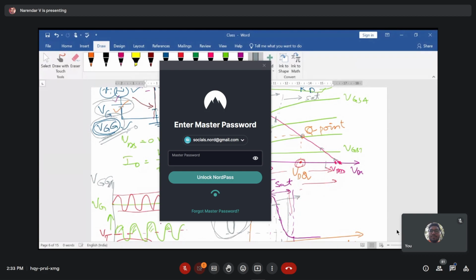So now we are fixing the value, that is your VG value, the gate biasing voltage that you are talking about here, means you are fixing at this point, let's say. Then your analog signal is something like this. After this point, the positive peak gets clipped because it is not recognized by the transistor.